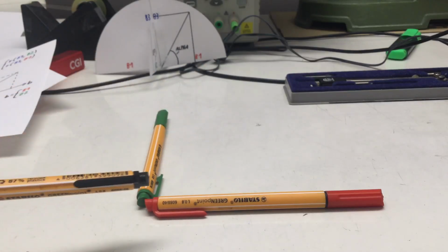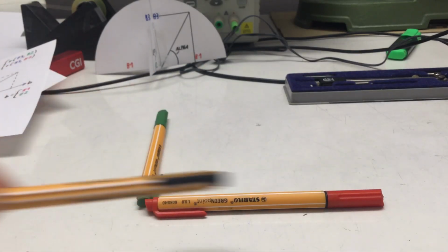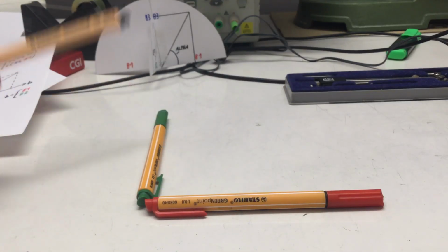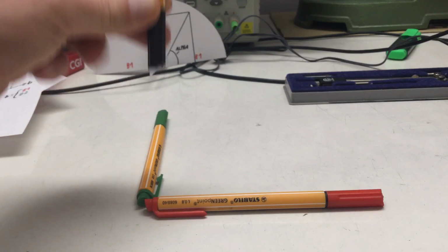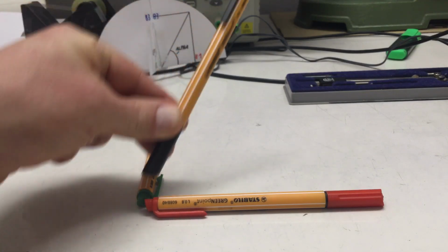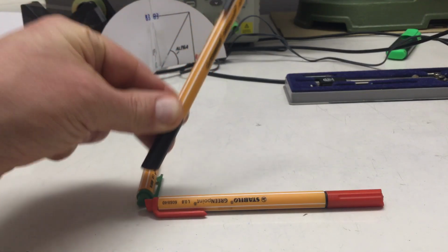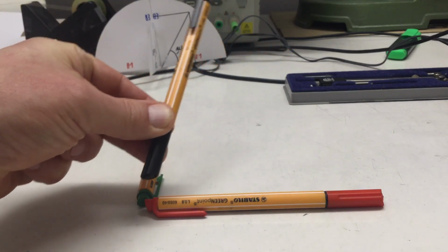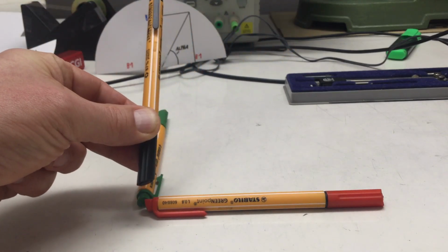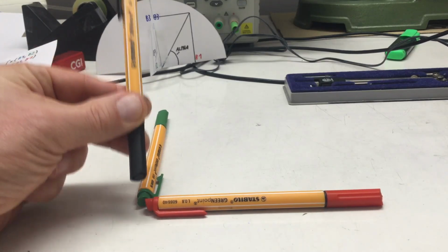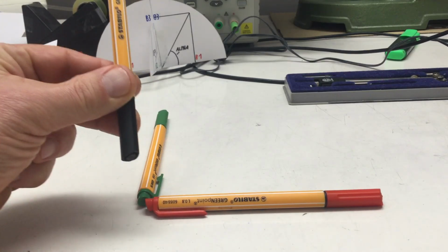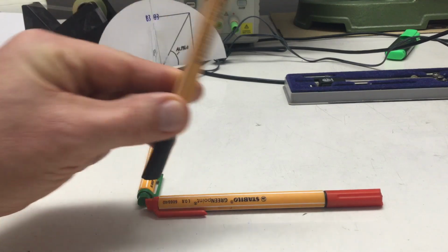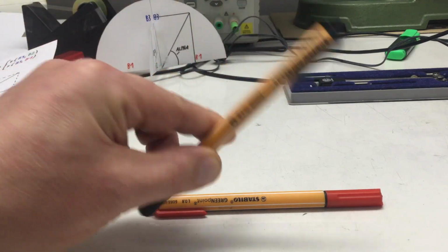In other words, if that is our B1 axis, usually X, and that is our B2 axis, usually Y, then the angle of the magnetic field is given by the angle over the x-axis and over the y-axis. And that's exactly what we want from a joystick. We want a signal for Y and we want a signal for X.